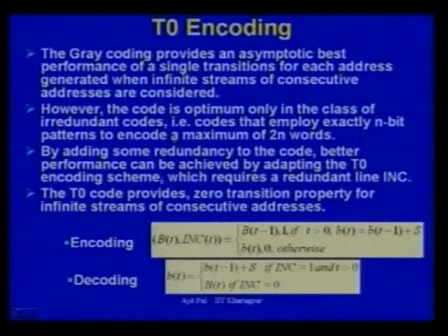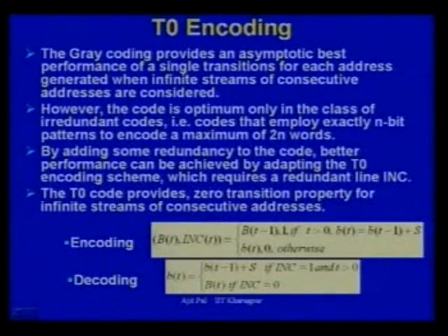If it is only an increment by a factor of s, as you know, in the case of instructions, the present instruction and the next instruction will differ in address by 4 or 8. In a 32-bit processor, the present address and next address will be 4 bytes apart. So you keep on adding 4. So, s is equal to the stride, that is 4, as long as it is a simple increase.